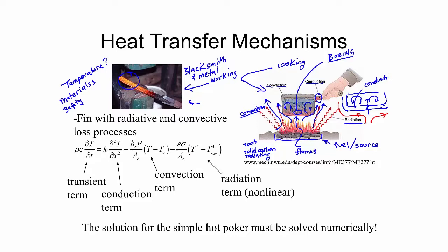And so we'll find out within the next few lessons how to construct an equation that would enable us to find what the temperature distribution is. And we'll show that there are several types of terms that could come about for this. We're doing a relatively simple approximation in this particular problem called the fin approximation. We'll talk more about what a fin is as we move forward.